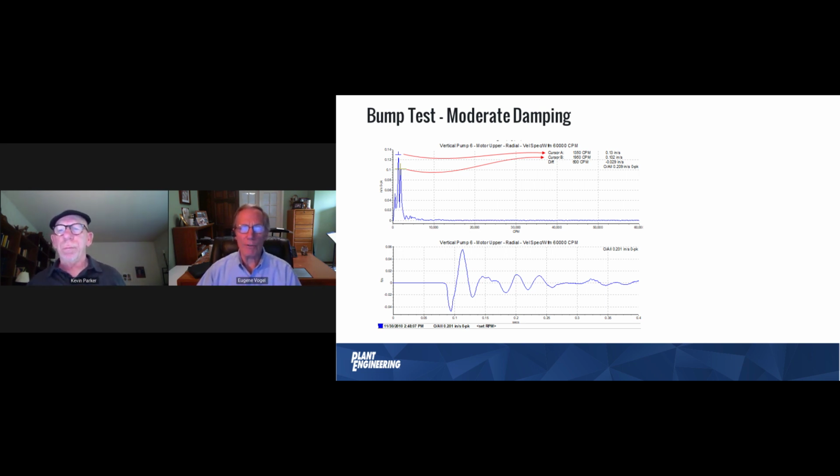So you have a graph of the amplitude and a graph of the phase as the machine speed changes. And that will show the change in dynamic response based on frequency, which is an excellent way of identifying a natural frequency. The bump test is simple. The Bode plot requires quite a bit more setup, but I would say that what you said is accurate.